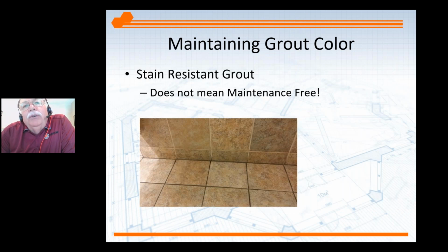I generally try to do residential, retail applications where the single component grouts really hold their color and are excellent to use. As we get into the healthcare facilities, back of house, schools, then I'm recommending epoxy grouts, and that makes it very easy to clean these floors. So here we have the grout on the floor much darker than the grout on the wall, but it's exactly the same grout, just not being maintained properly.